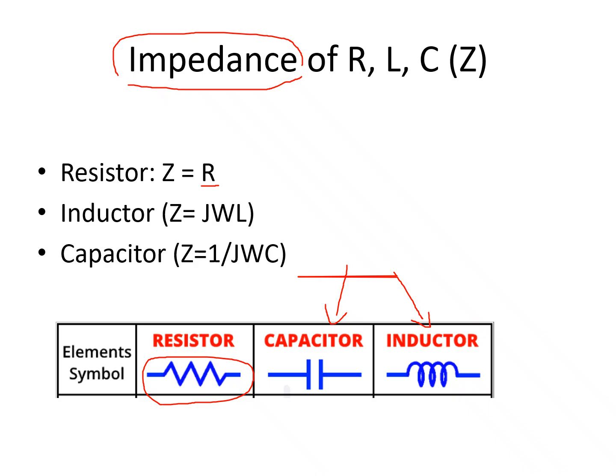And these are the circuit representations of a capacitor and an inductor. Just briefly, the impedance of an inductor is jωL, and L is the inductance of an inductor. And for a capacitor, it's the inverse of this value. So the impedance of a capacitor is 1 over jωC, and C over here is the capacitance of a capacitor. We will delve more into that in upcoming lessons.